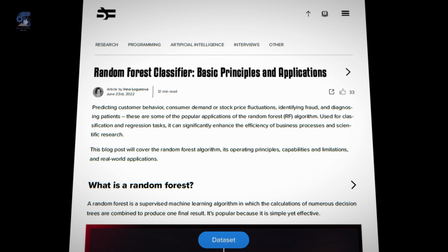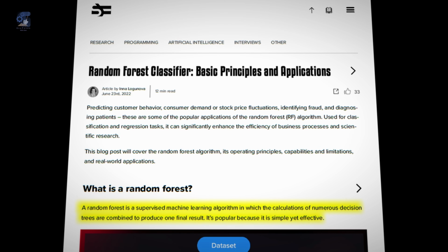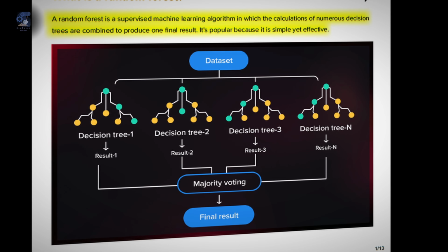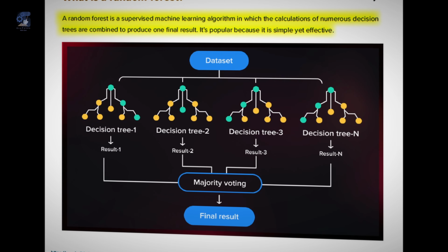Random forests is an ensemble learning method that combines multiple decision trees to improve accuracy and resist overfitting. They are frequently recommended as the superior method for identifying soil types based on cone penetration test data, predicting indices like maximum dry density, optimal moisture content, and the California bearing ratio. They are highly effective at predicting shear wave velocity using minimal input features from CPT soundings. Moreover, they can generate precise maps to assess the likelihood of slope failure.